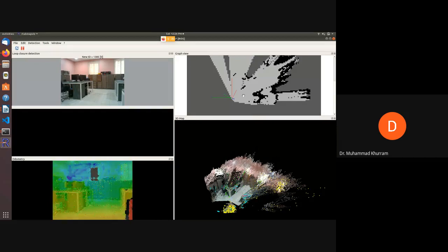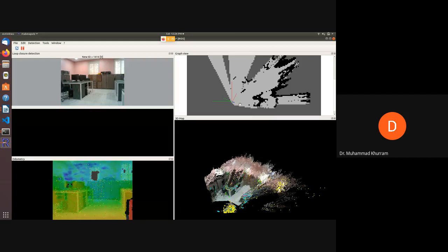The occupancy grid is a map of all the static objects in the environment surrounding the vehicle. Depth cameras and LiDARs are prominently used to construct the occupancy grid map. A set of filters is first applied to the depth camera data to make it a usable occupancy grid. For example, it identifies the drivable surface points. As you can see in this gray map, if it is not making sense to you, I will explain it. These light gray regions are telling that these are the traversable regions.